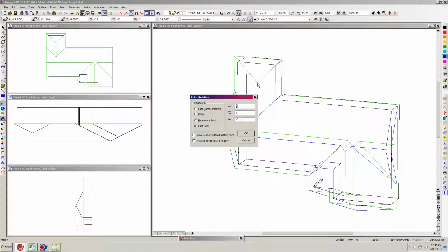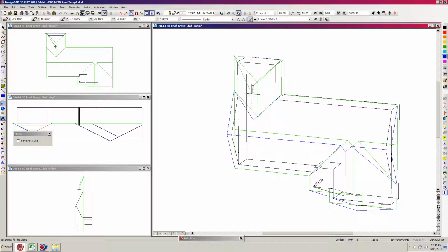Gravity move, 0, 0, 0, and 0, 0, and then hit tab again. And here you can see right here where it says last, it's going to set it from the last point. We actually want the last cursor for this, so we set it. Click on that radio button and click OK, and here we are. And so all I have to do now is just click my scroll button, and I have my plane there. So the rest is really pretty straightforward.